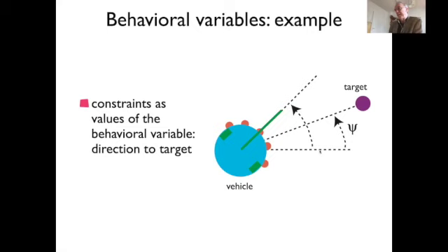So the invariance is here expressed by the fact that this angle psi is the same no matter what the initial heading of the vehicle. So if the vehicle is initially heading a very different direction, it's always the same heading angle that is the target. This would be hard to express on the vehicle. The only way to express it on a vehicle would be to say, well, I want the target to be at 0, my nose being headed to the target.